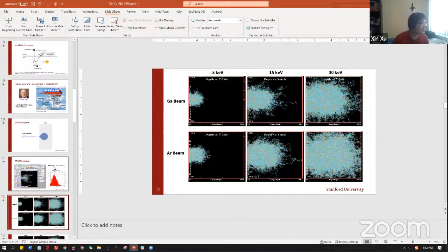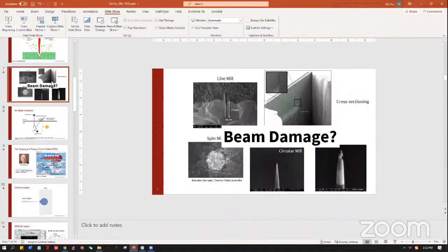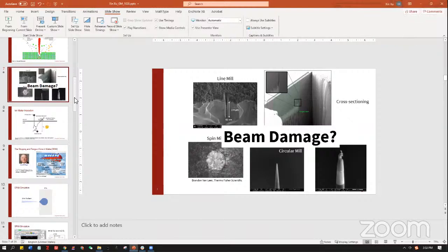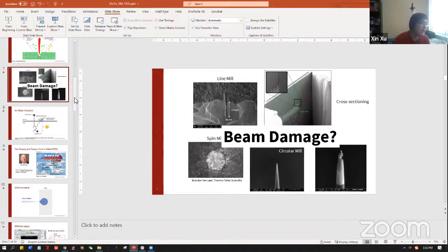So are you doing the etching or deposition? Deposition of metal, let's say, on some semiconductor. So this is a very good point. If you want to do a very sharp deposition, I would recommend using the ion beam. You definitely need to use a very high voltage and less current because the beam profile is very sharp and narrow. For this deposition, you can definitely do features of 100 nanometers.